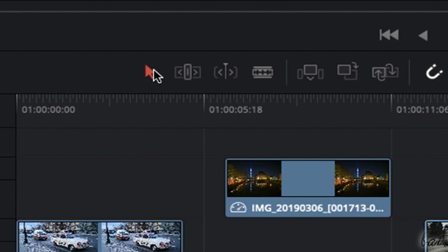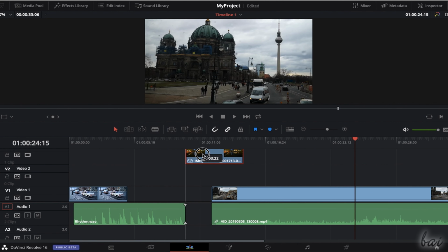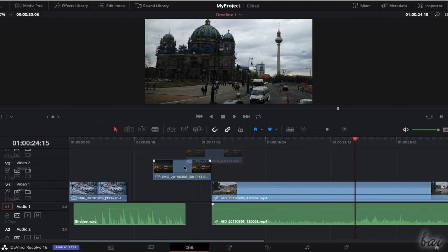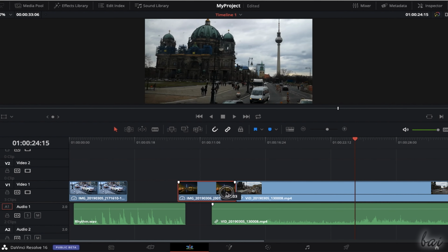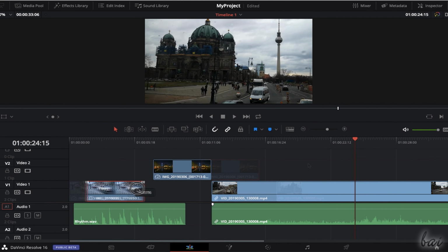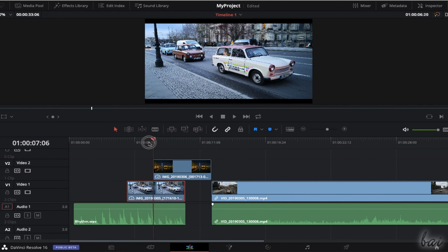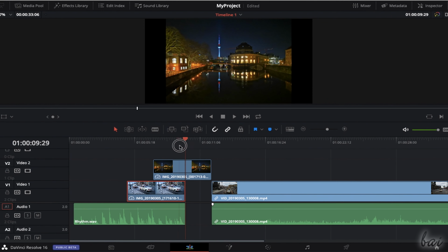Now let's see how to edit clips with the selection mode enabled. To move any clip in time, just click and drag it within the same track or in another one. If the track does not exist, it is created automatically. Make sure not to overlap clips in time within the same track, or one of these gets cut. The video tracks order also fixes the order of visibility between the visual clips that overlap in time on different tracks.